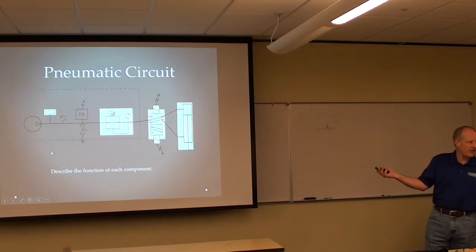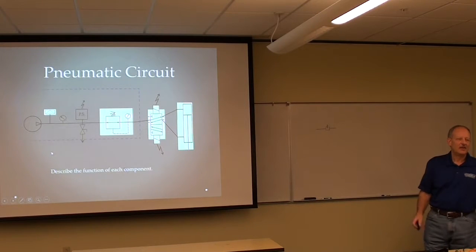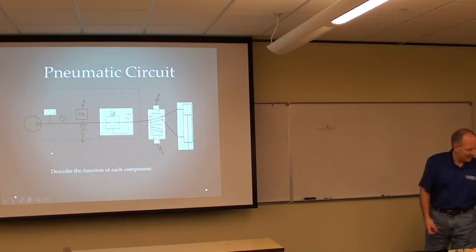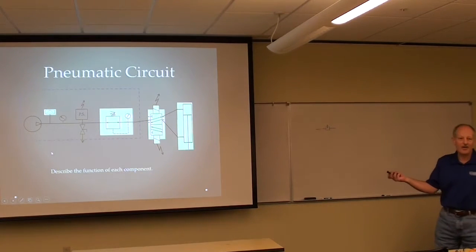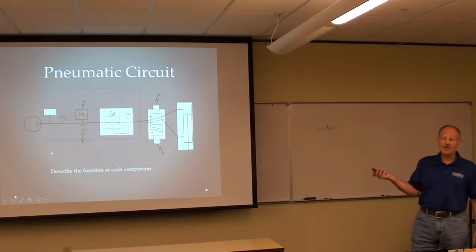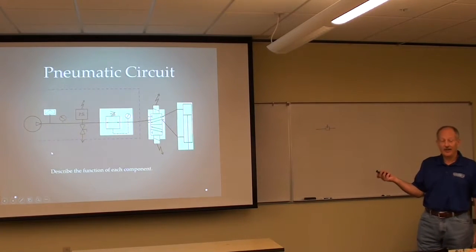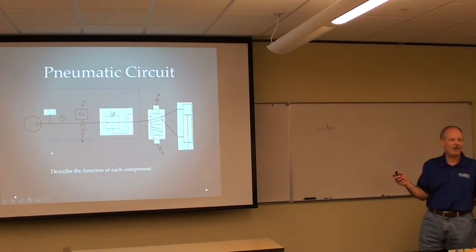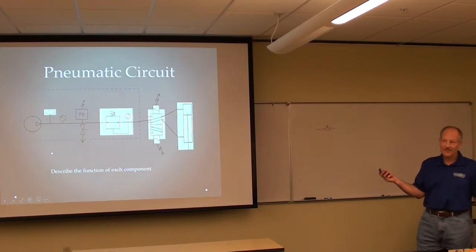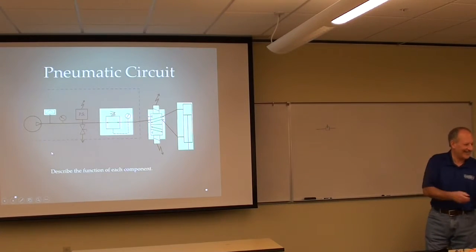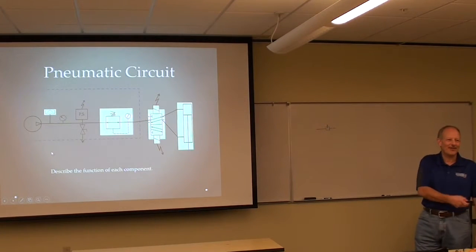Would you add anything else? A tank. Why would you add a tank? So your compressor isn't constantly running and you have a solid working pressure. And why is that important? Because you don't drain the battery. Even the little compressor they've got makes a difference in how much it pulls down the battery. In previous years, we've seen a difference in the speed of the robot when the compressor's running and when it's not. It's like shifting gears. You need a low gear, just turn on the compressor.